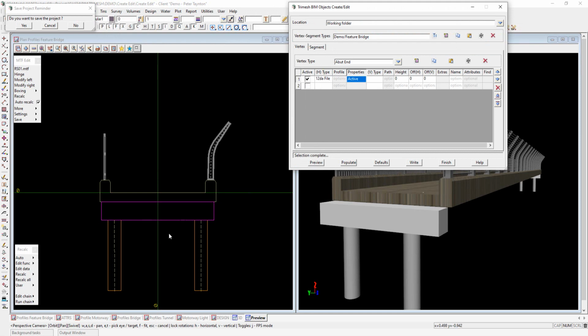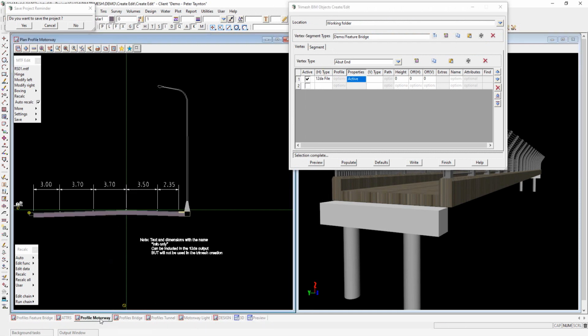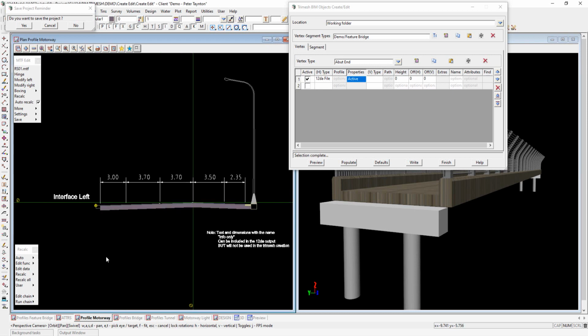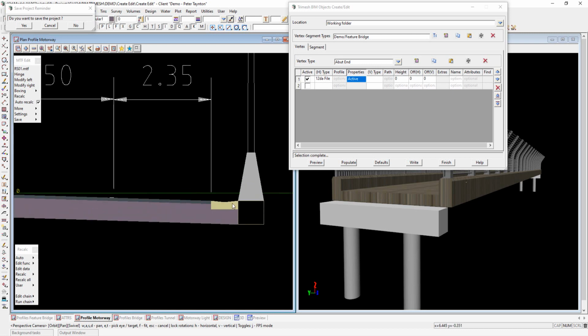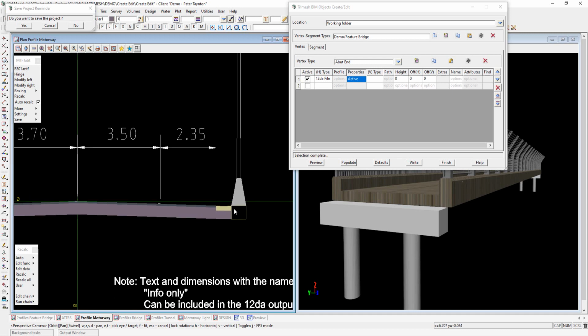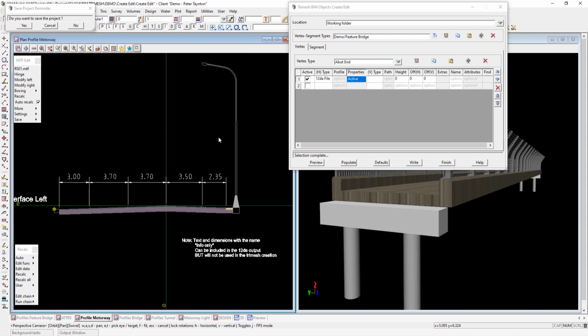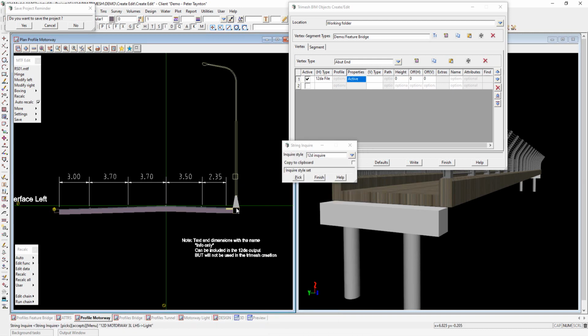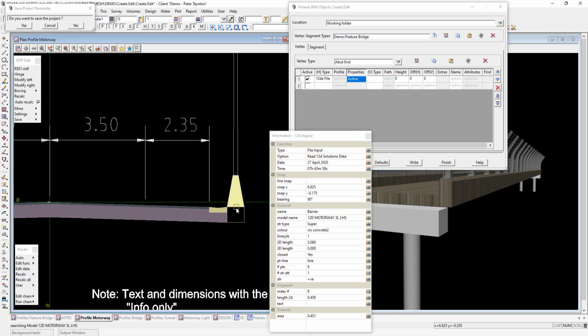So again, for bridge tiles, we can then look at the same profile idea for a motorway. Same process. We've drawn a shape. 0.0 is going to be our reference alignment string. We've got definitions in relation to pavement, curb, some barriers, island, median barriers, even a light profile. If I pick on those, they're just simple shapes. Light. There's a shape in here that represents the barrier.